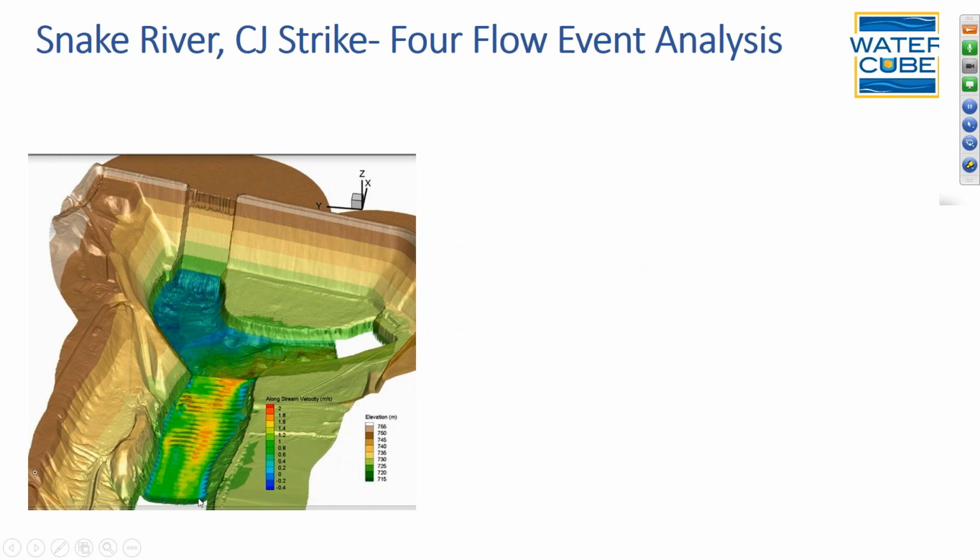The velocity index rating got very bad. And what you had happen is, depending which turbine was running, your velocity distribution of the channel would change. So they collected a lot of data to look at what is happening and how do we move or redo this instrument to get a better idea of what's going on.